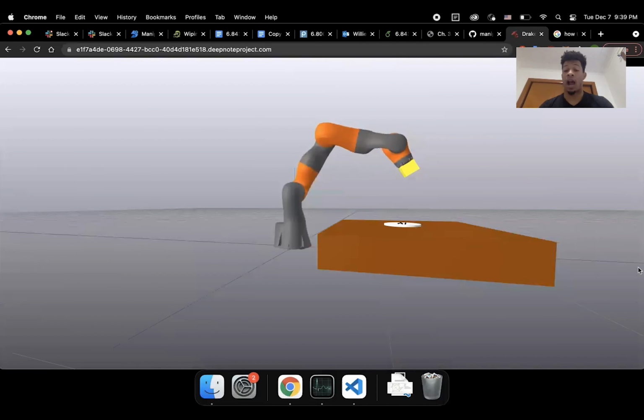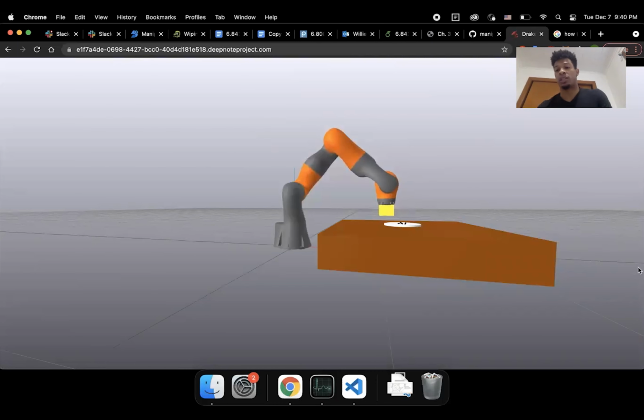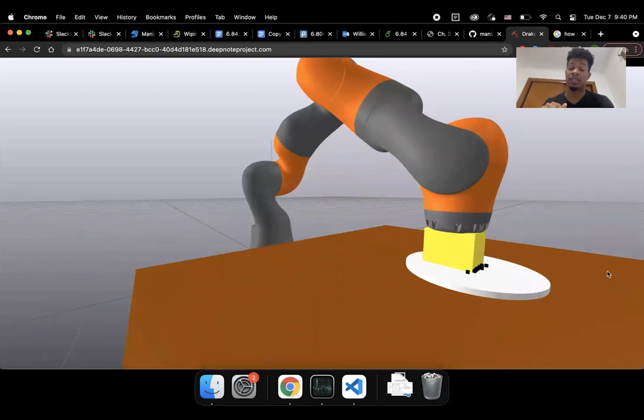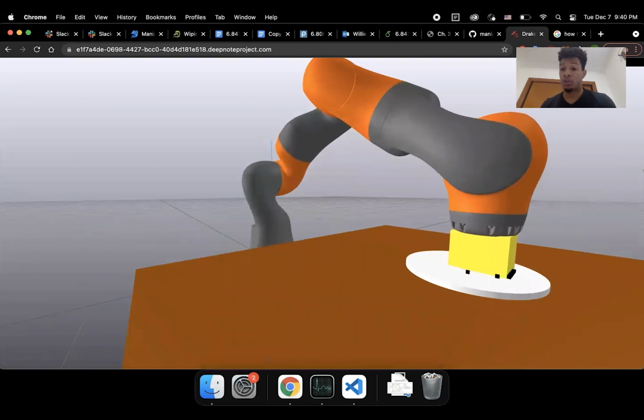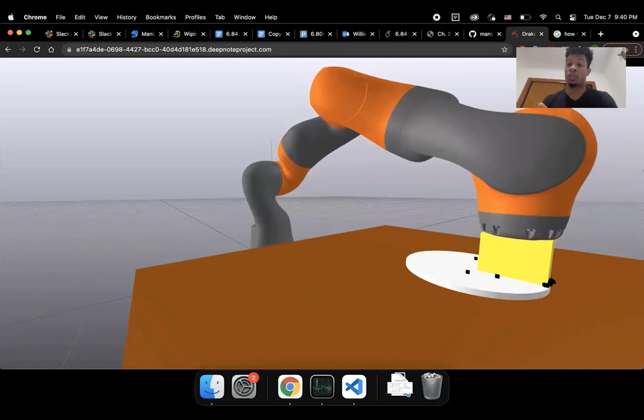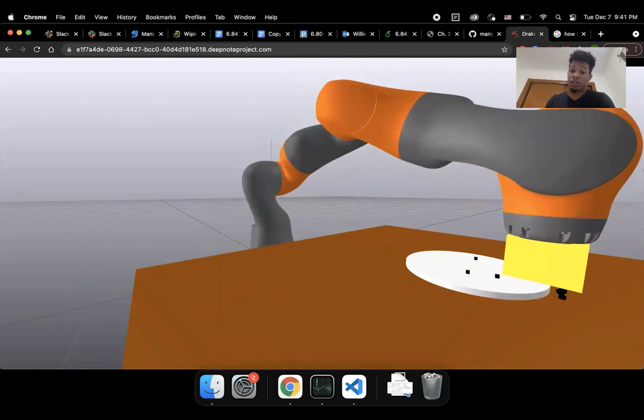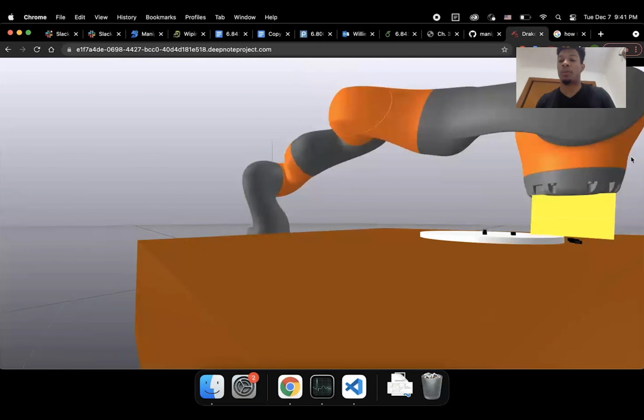Now that we have a simulation, a hybrid force position controller, and a wiping trajectory that we want to move along the table, we can now talk about our overall control strategy. How it works is from the initial configuration of the gripper, it moves to a location on the table using pure position control. When it's at that location, it then switches into our hybrid force position controller, which moves along our wiping trajectory that is given by our optimizer, while maintaining a force in the Z direction that is weak enough to allow for moving along the XY direction, while also strong enough to make sure that our plate doesn't move when we're doing the wiping motion.